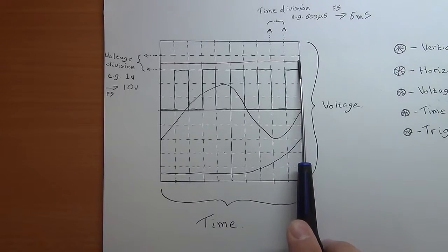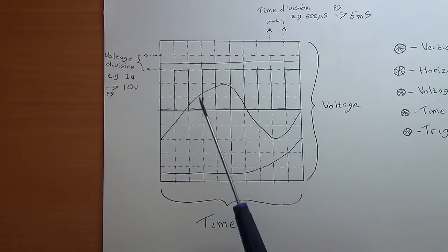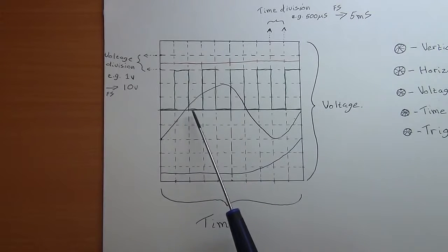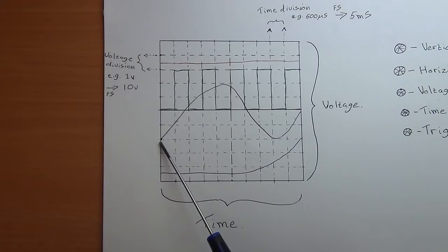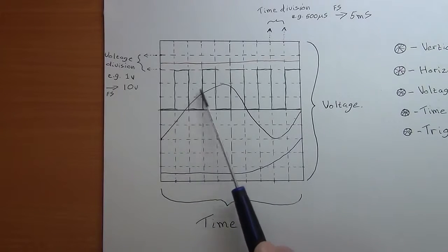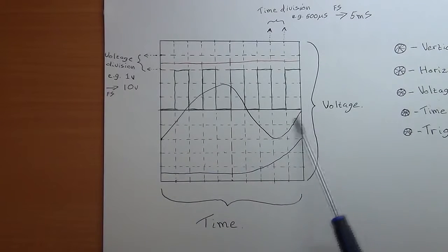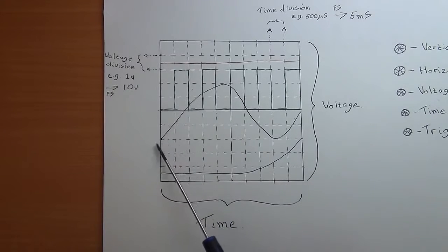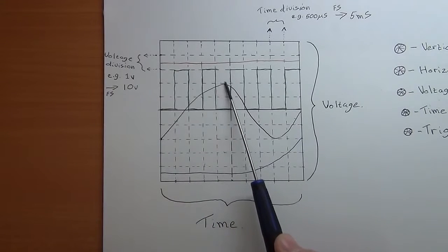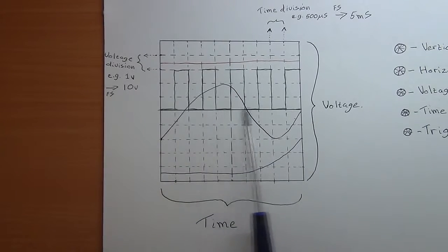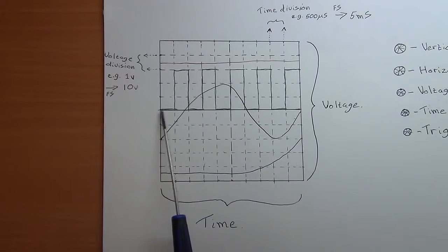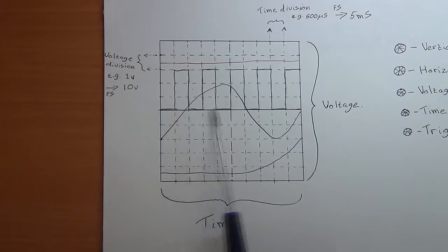It's just going to be a straight line. If you had to connect your oscilloscope up to, let's say, if you could connect it up to your mains electricity safely, and you're looking at the signal of the AC, you would see a sinusoidal wave appearing on your scope. So it'd be something that would be going positive and then coming down negative. Now, something else to highlight is that you have a kind of middle line on your oscilloscope, which in essence represents your kind of 0 volt line. So above would be positive, below would be negative.